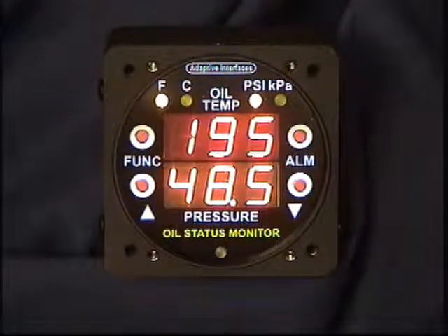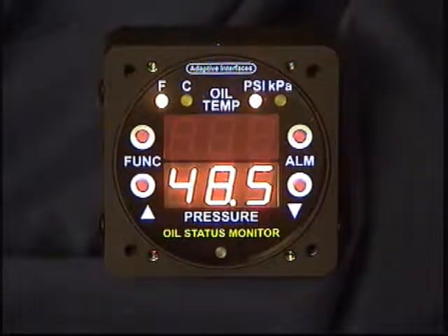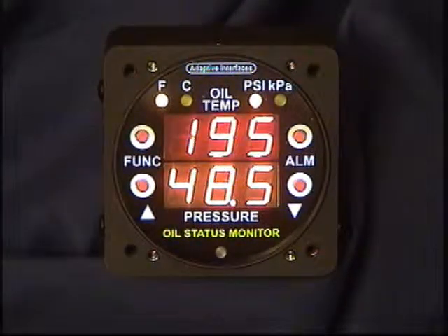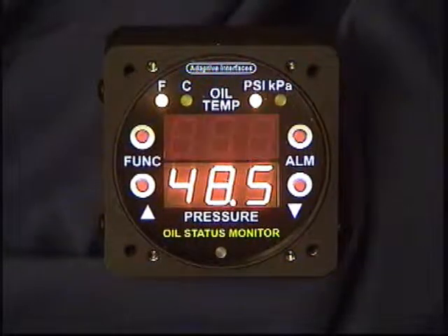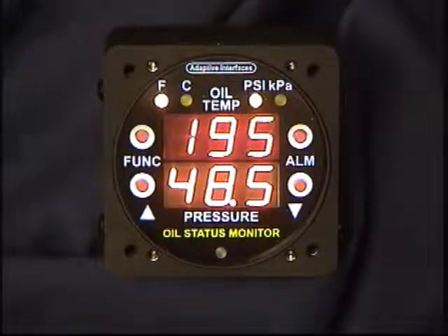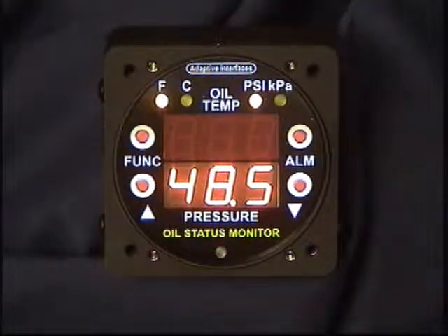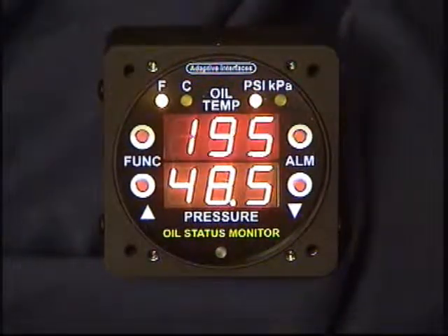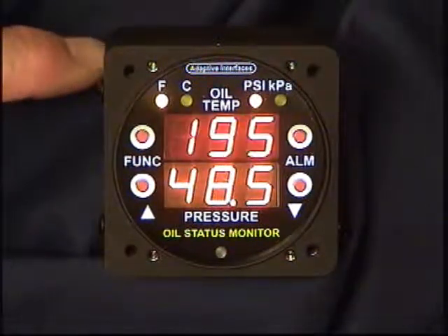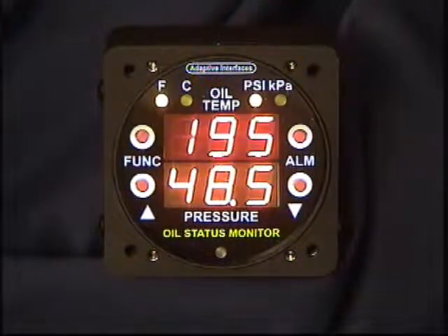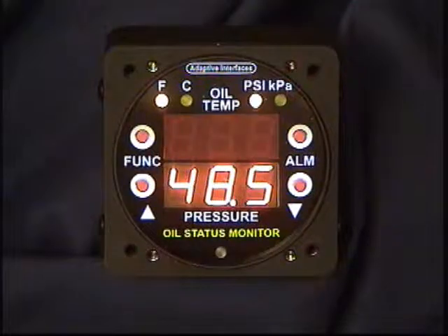Again, the alarm was set at 190 degrees Fahrenheit and the instrument is reading 195, and this is what happens when it is in an alarm condition. This display brightens up to full brightness, and the value that is showing the alarm condition, in this case the temperature, is flashing to let us know that we have a high temperature. Also, there is an electronic output on the rear panel of the instrument that has been turned on that can turn on a warning light or a warning buzzer as well.